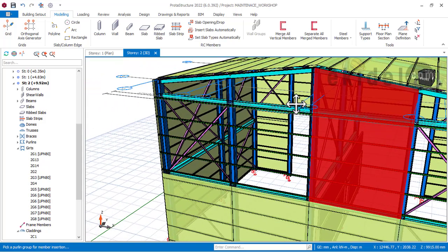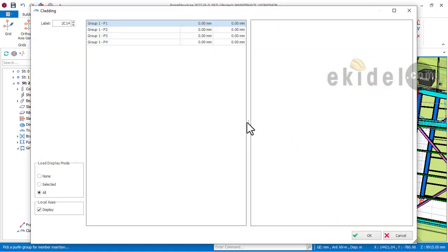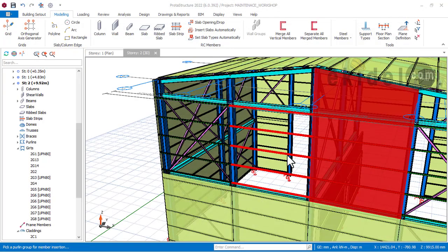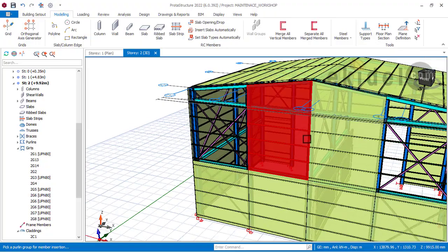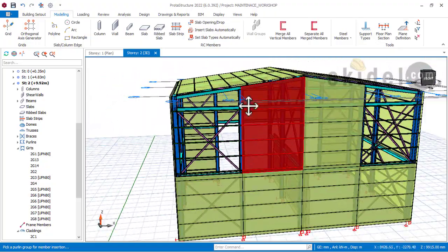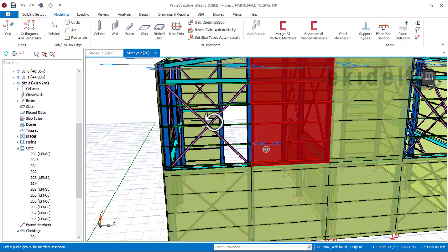Okay, now I told you again that cladding has what they call anti-clockwise when you're working with cladding that has a slope. So for this other one here, to put the cladding here, I have to make it a reverse. That reverse will just be P1 0, P2 0, P3 now becomes minus 565, and this now becomes 0, and I'll click OK. That's fine. It will just fit in again. So you can now see that we have created another cladding for this back here.